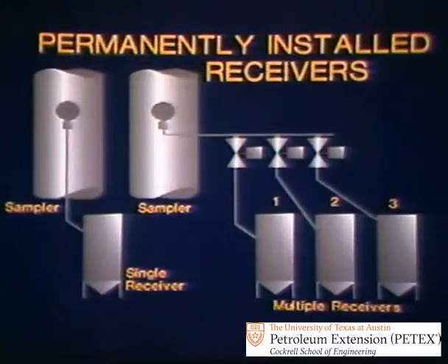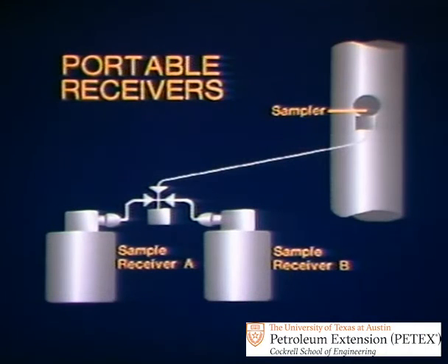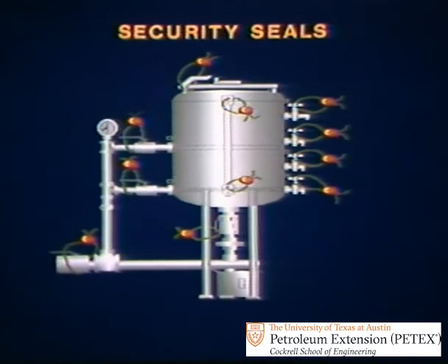Sample receivers can be permanently installed and can be single or multiple units. Multiple units are used when different crudes or products are sampled and it's necessary to isolate them. Portable sample receivers are also available in both single and multiple units. All sampler controls and access or withdrawal points should be sealed to disclose any tampering. The quality of the oil or product greatly influences volume determination, specification compliance, and in some cases pricing. So security is important.